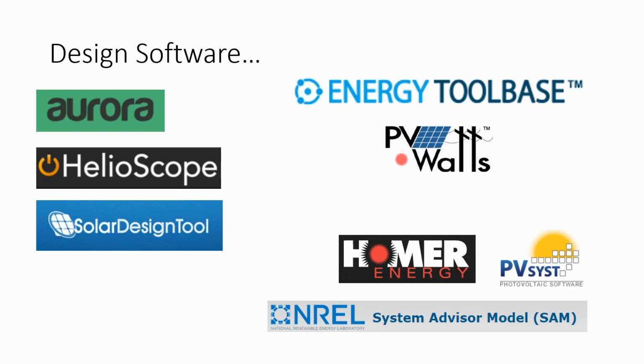PV Watts' big brother is called SAM, the System Advisor Model, and you can also download it. It's put out by the National Renewable Energy Lab, and it has a storage component that you can use to not just do solar, but also put in your building interval data and your battery bank size and do some free energy modeling that way.